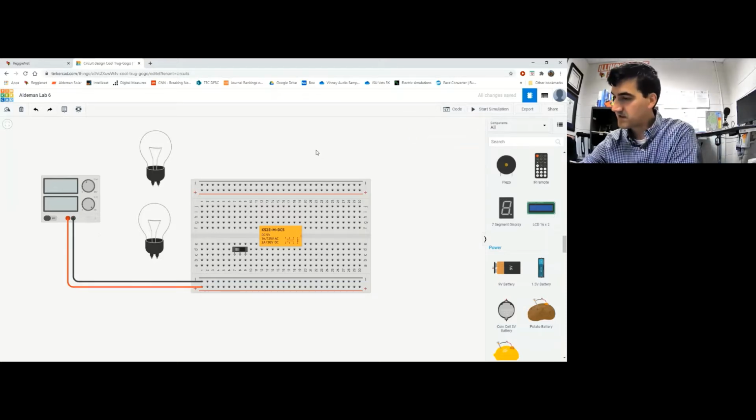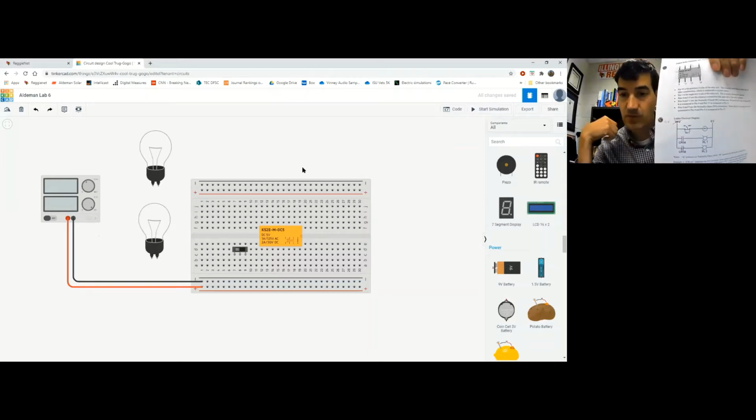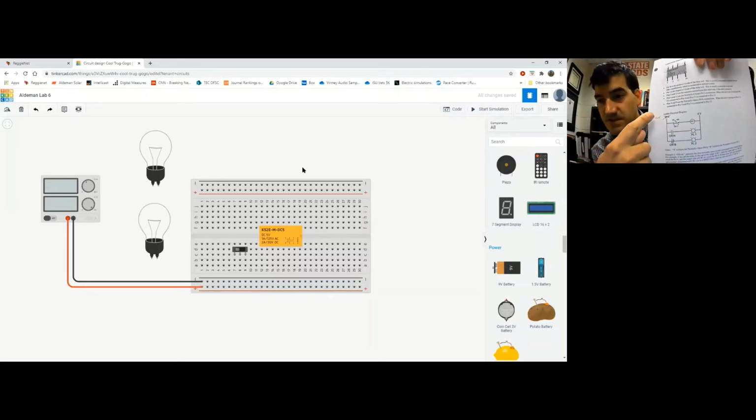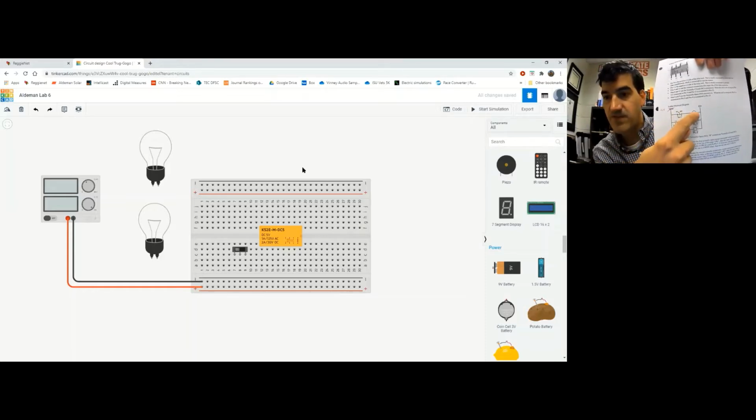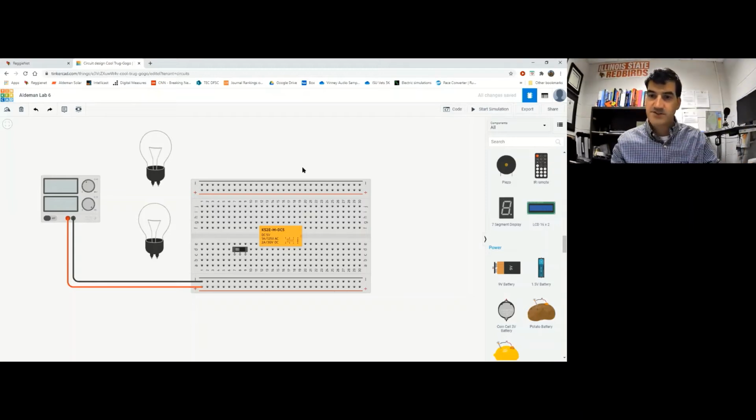All right, now I'm going to keep one eye on my TinkerCAD circuit and one eye on my ladder electrical diagram. All right. So the first thing, I'm looking at the first rung. I'm going to go rung by rung. Okay. And that's the way I'd recommend you do it. First, just look at this first rung and complete this first rung. And within that rung, the first wire we've got to look at is this wire right here. That goes from 24 volts, that's the positive side of the power rail, to the common or the input of our slide switch.